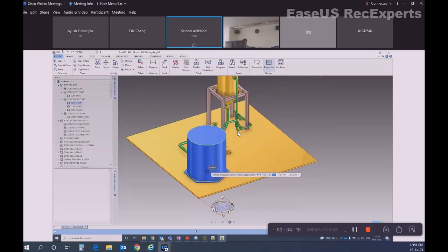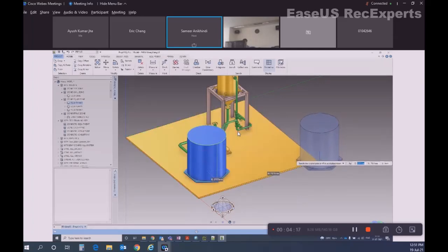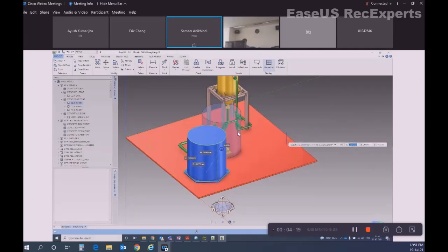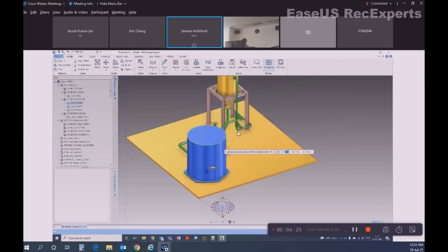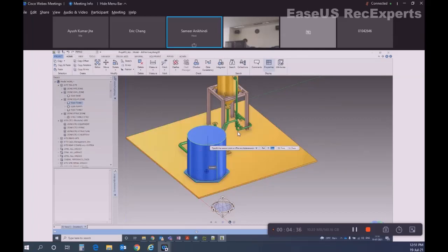This is the base point, and as soon as you select, it will give you an image around copying it. Sometimes it appears to be jammed somewhere and is not moving. This is because of your snap. The snap is active, so it is snapping to some points. To have better visibility, you can turn off the snap by using the F3 key.